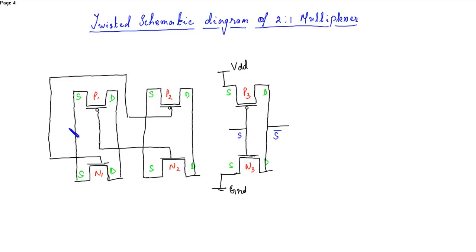As we know, in the first transmission gate, at the gate terminal, S bar is connected, that is over here. S bar is connected, and to this S is connected. To transmission gate 2, S is connected. To transmission gate 1, S bar is connected. So this is poly and this is metal. Over here there is poly. S bar, this is poly, again poly.